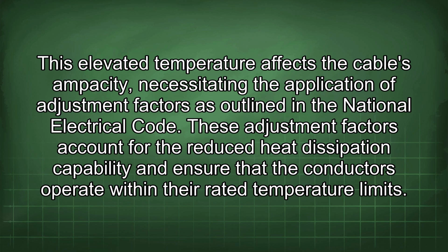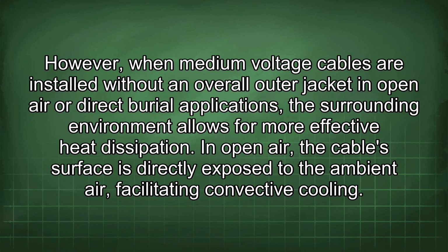These adjustment factors account for the reduced heat dissipation capability and ensure that the conductors operate within their rated temperature limits. However, when medium voltage cables are installed without an overall outer jacket in open air or direct burial applications, the surrounding environment allows for more effective heat dissipation.